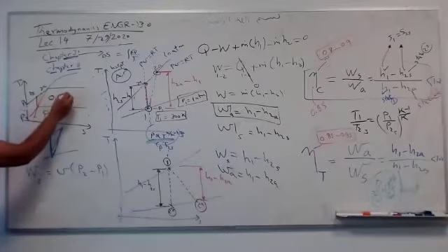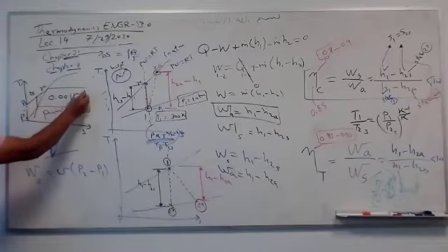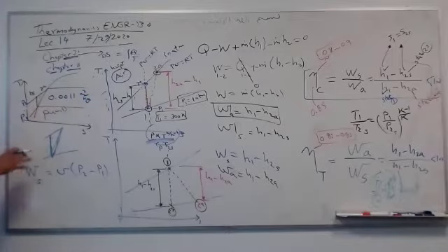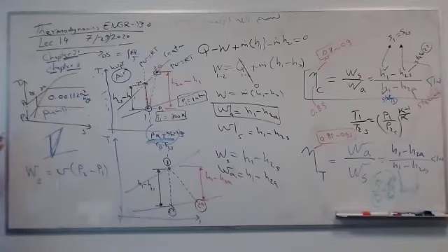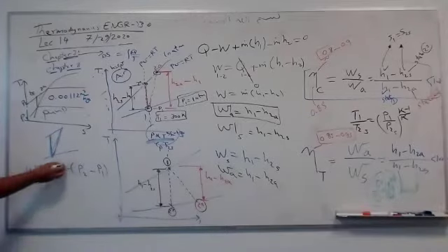Let's say the specific volume is something like this. When you compress from 1 to 10 atmospheres, it doesn't change a lot. It's almost the same, 1 or 2%, or even less. For 10 atmospheres, just 1%, or even less. So you may assume this is constant.